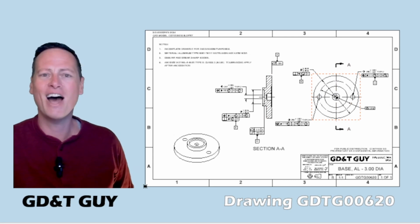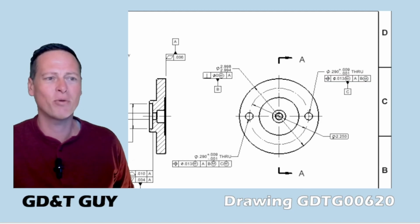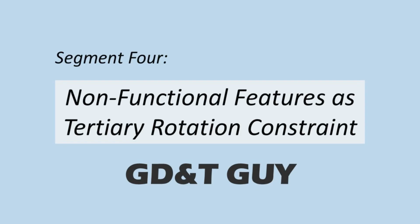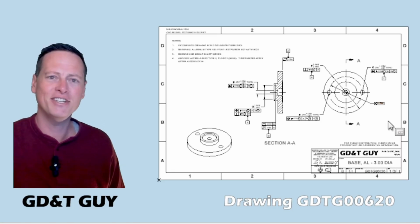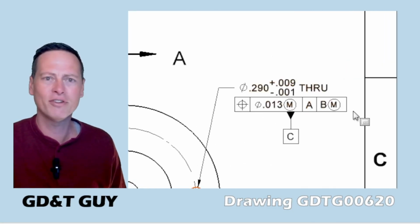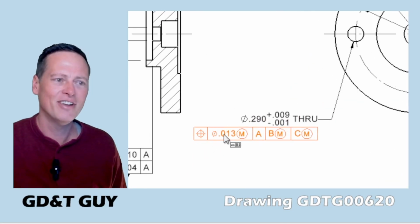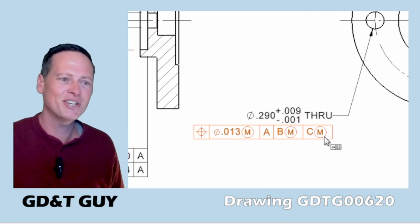What I think you should not do, and what I see all too often, is this idea that I'll just pick one of these holes and I'll call it my Datum C feature, which is what we'll get into next. So here we are on drawing GD&T 00620, where we have a call out for the hole on the right, which we've decided to call the Datum C feature. And then there's another call out for the second hole, this one referencing Datum C as tertiary.